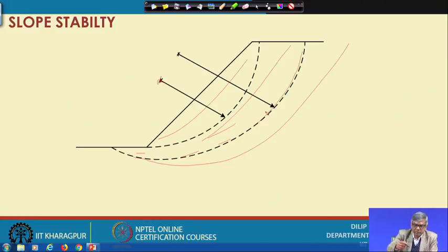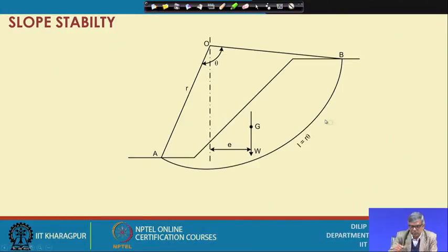So, this is the way we generally follow. Typically, suppose the final slip surface is something like this, and this is the slope, with a slope angle, and this slip surface has a certain length equal to L. If I consider it as a portion of a circular arc, then the length will be r into theta subtended here; r multiplied by theta is the circular arc length.